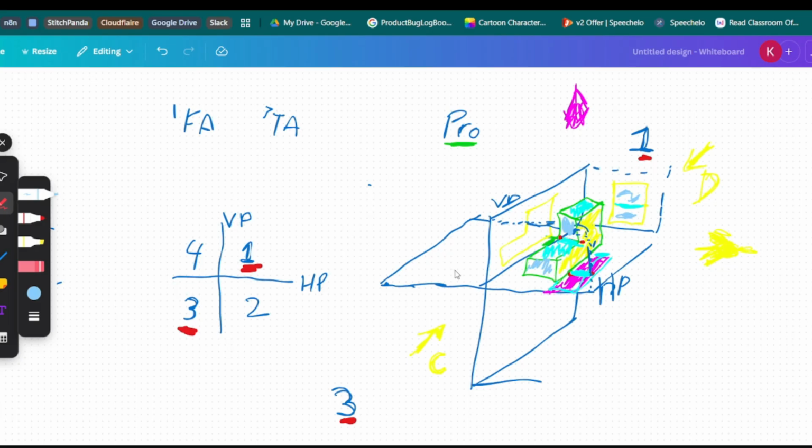Now, yes, my sketching will look a little sketchy, but at least we understand that this is being projected onto this side. Now, this particular view, meaning from the direction D, is not going to be anything associated with this. In fact, the direction will determine what turns into a hidden line. So let me just come at the side here. Let me just bring this across.